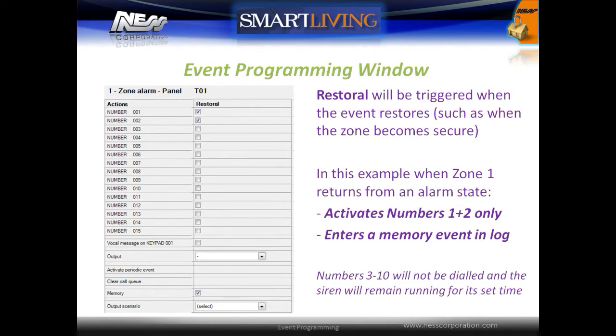Restoral is triggered when the event restores, such as when the zone becomes secure. In this example, Zone 1 returns from an alarm state and activates telephone numbers 1 and 2 only and enters a memory log event. Phone numbers 3 through 10 will not be dialed and the siren will remain running for its set time.